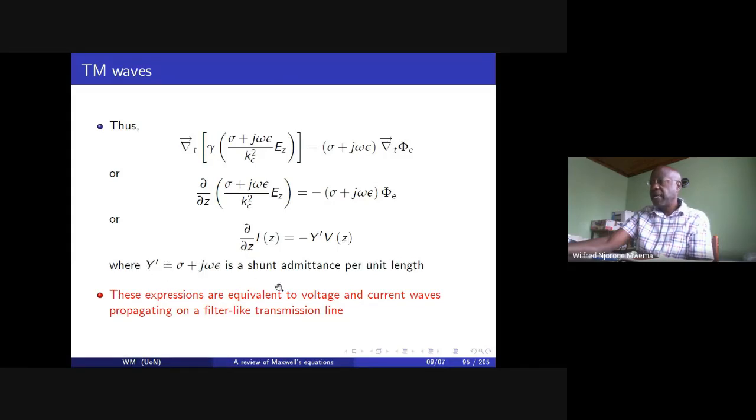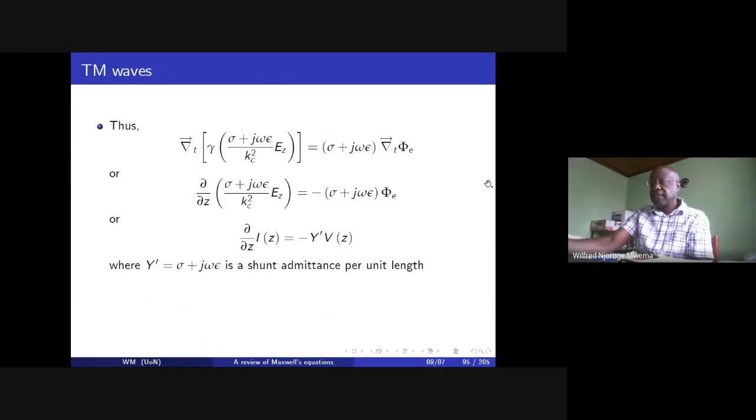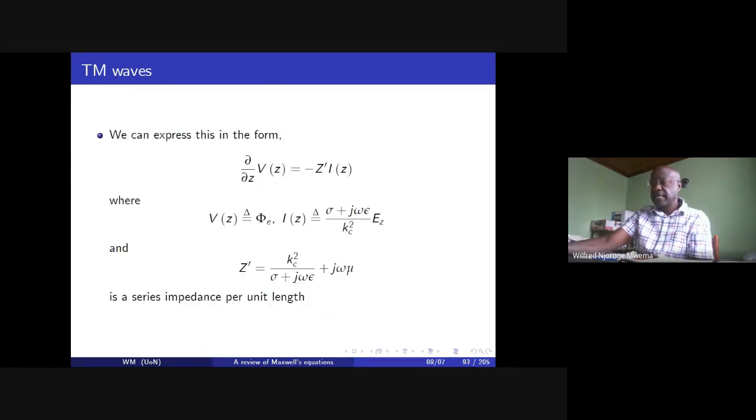of gamma Y. If you look at the impedance Z prime, we see that this value is a constant divided by area, so to speak, and this is a conductance, and therefore 1 over conductance or 1 over admittance is the same as an impedance. And therefore we can see that this is an impedance or a capacitive kind of impedance in series with an inductance. Okay, so that's why we are calling them filter-like.